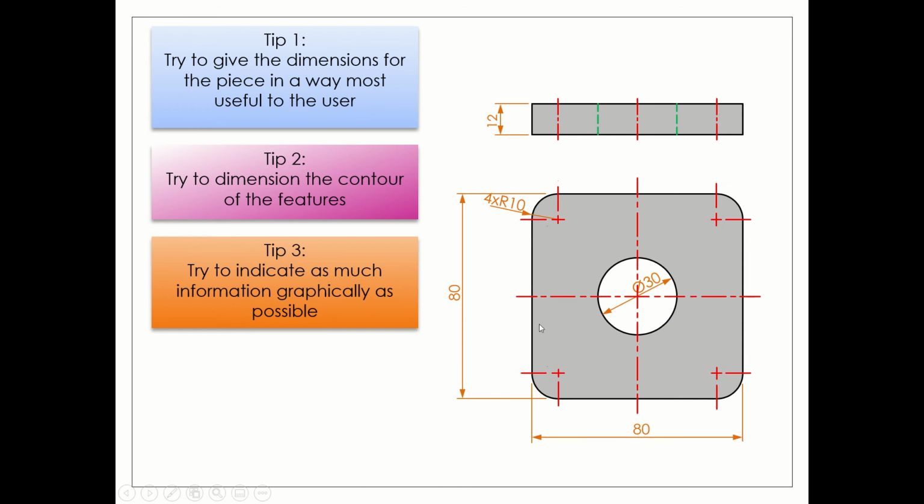And in fact, you can actually draw two little dash marks here, and then across here and the top here, indicating that it is the dead center of the piece. Now what you're doing is saying it explicitly. You're not making the person assume that it's centered, because if they're assuming it, that means you haven't told them, which means you've fallen down in your drawing.